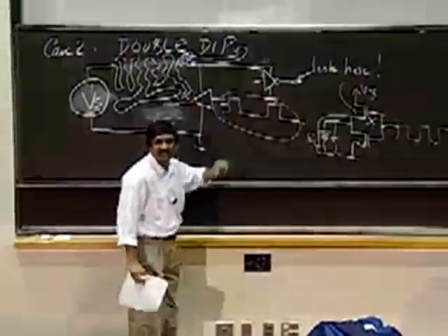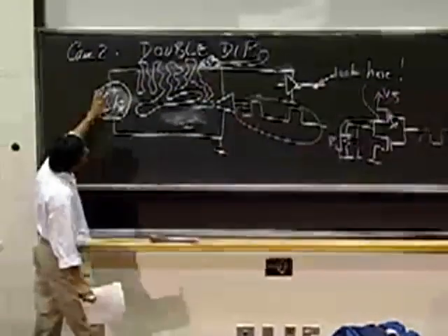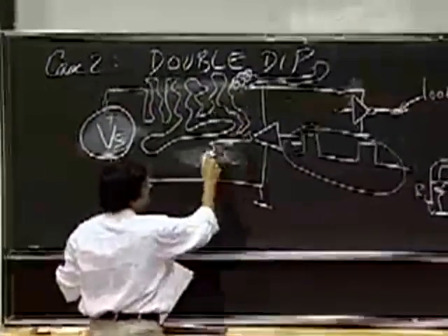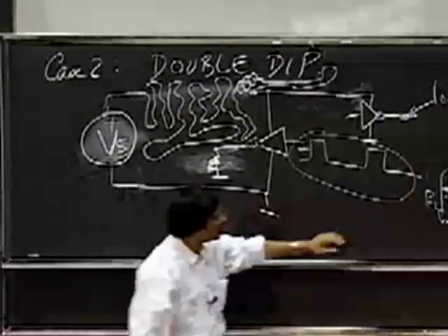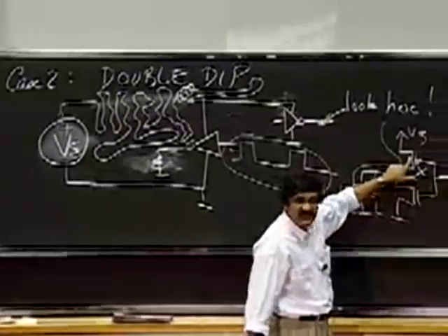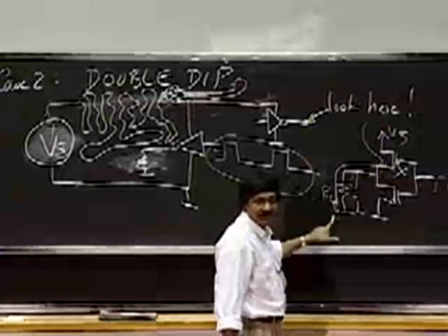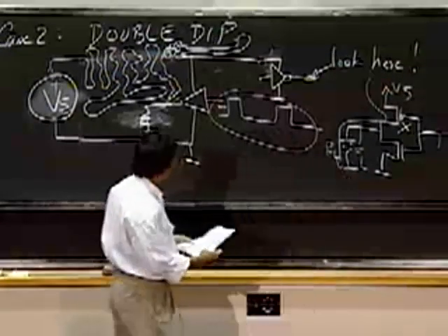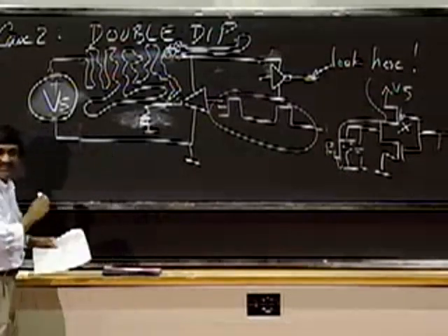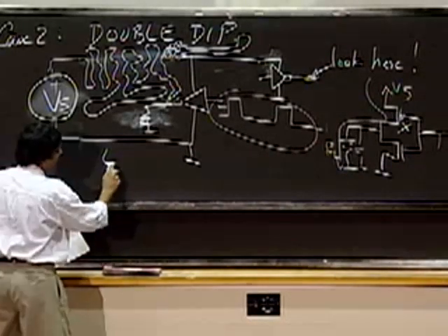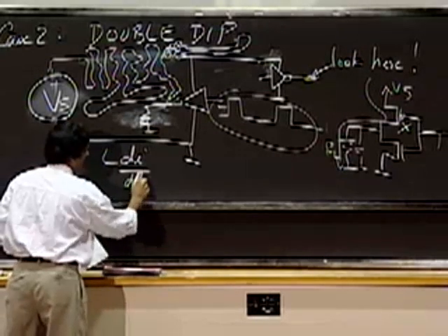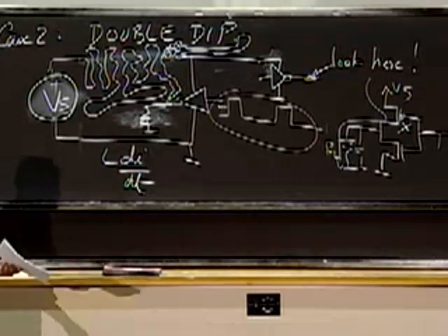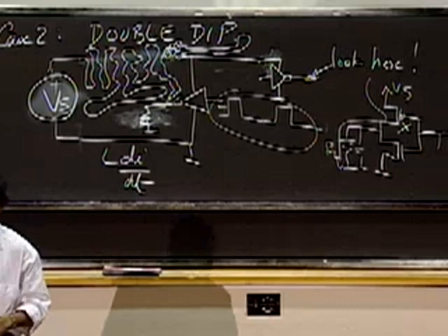So here's what's going on. There's an inductor here, and when I put a 50 ohm resistor here, when the PFET turns on, it draws a current. If it draws a current, remember that across an inductor I have a drop, and the drop relates to di/dt. Remember, for a capacitor, the current is C dV/dt.